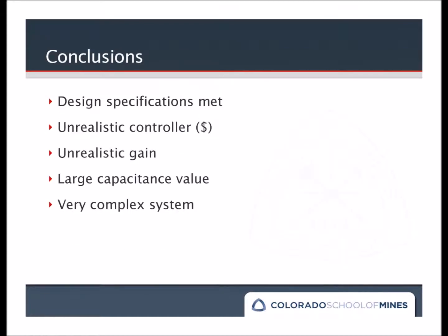Ultimately, we reached several conclusions. Firstly, we met all of our design criteria. The system passes all of the frequencies in our range and eliminates signals outside of that. The gain and phase margins are at acceptable levels per our goal. The system is also stable on its own, and we determined all of these using MATLAB and SisoTool.